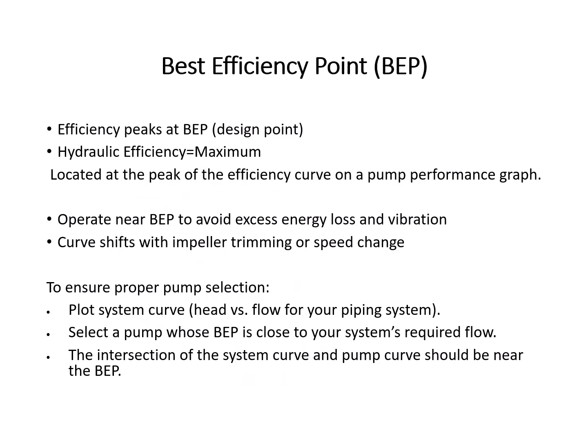Now let's talk about the best efficiency point, since we are speaking about efficiency. The best efficiency point is where magic happens. Maximum output with minimum waste. Operating far from the best efficiency point can lead to vibration, wear, and costly energy bills. So always try to be on the best efficiency point. At the best efficiency point, the hydraulic efficiency is maximum.